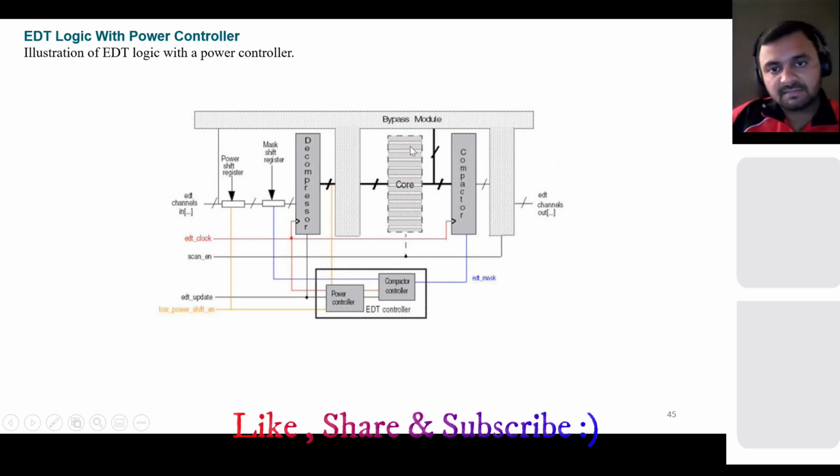Basically, you have the internal chains and you want to control the power, since patterns are applied from the EDT channel in. So you want to reduce the power. While shifting, we reduce the toggling, because if your signal toggles more, it will take more power; your core will take more power. So we control that toggling here, and for that we use the low power shift enable. If you are designing your chip for a low power application, you use this low power shift enable. Basically your shifting will be done with less toggling, and if you toggle less, your power will be less.